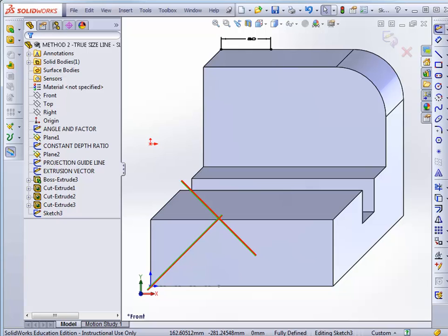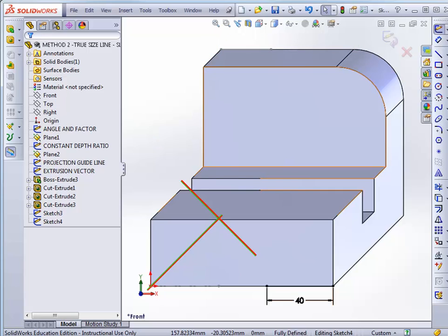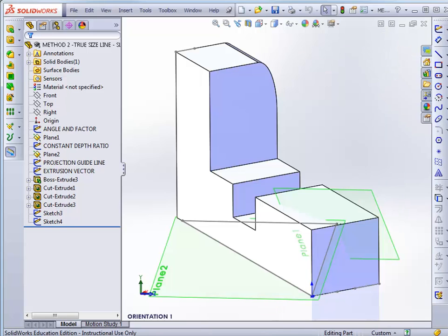In the oblique configuration, a first line is sketched on the top surface and its length dimensioned. This is important to remember as point-to-point might cause some problems. A second line is placed on the front face and again its length is dimensioned. The next step is to create a reference plane through 3 points.